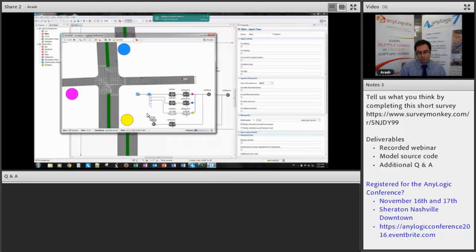By this type of construct, by this type of flowchart, we can put a portion of the cars on a specific lane. So as you can see here, we have 4 lanes, 0, 1, 2, 3, and I will generate some cars here, but I use the source from the process modeling library. So when you're generating cars from this generic process modeling library source, we haven't put the cars on the road network yet. We are actually going to put them on the network with this car enter block.